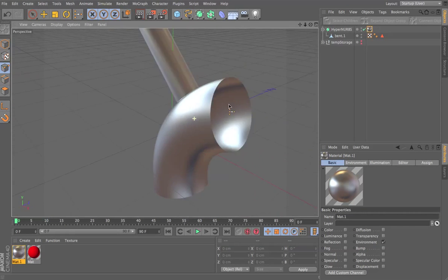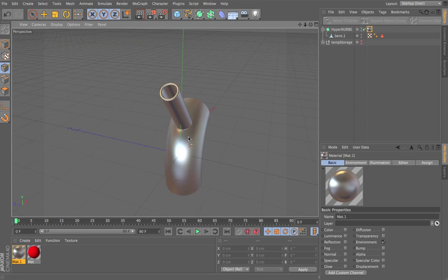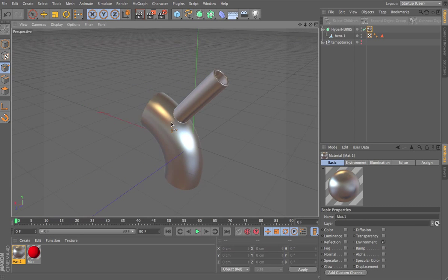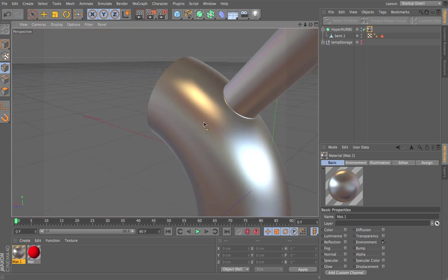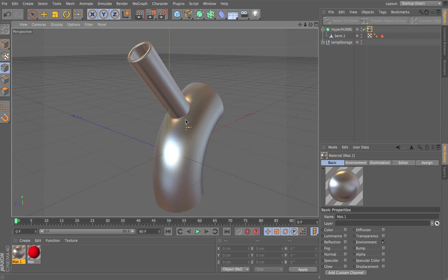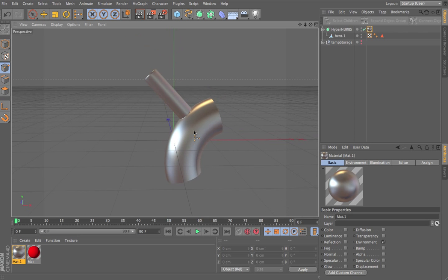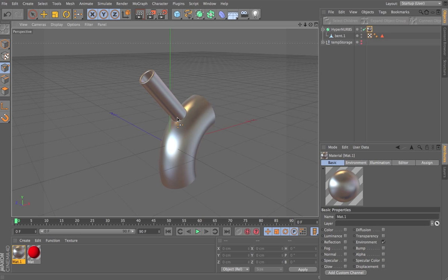Clean and brilliant. So, you know, with all the explanations and so forth, it doesn't take that long to do, does it? Yeah, but anyway, I hope this kind of helps. Never, ever, ever forget that you have to prepare. You cannot just go there and create any arbitrary number of rotations and expect objects to fit properly together. That cannot happen. Making sure your topology is proper and compliant from the beginning is a huge time saver, and sometimes it's the only way.